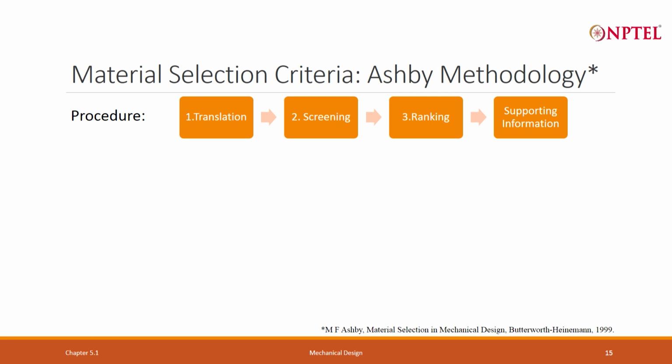So, what is our basic function here? Provide the support in the base plate. If we talk about the basic function, it is to provide the support to the weight of the cell. What we do not want is a deflection to go beyond a certain limit.